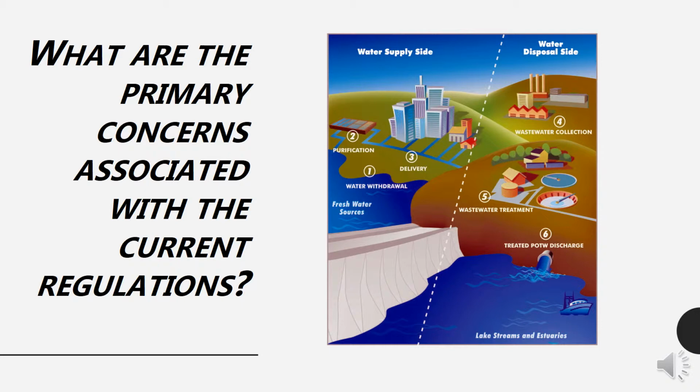Unfortunately, there is strong scientific evidence that the current Stage 1 and Stage 2 DBPRs fail to protect water consumers from exposure to potentially harmful species and concentrations of DBPs. U.S. regulations of DBPs have been updated several times since the first discovery of DBPs in finished drinking water in 1974. However, as argued by Singer in 2006, these changes have consistently failed to consider scientific evidence showing that the 11 regulated DBPs are inadequate surrogates for the complex mixtures, potentially hundreds of DBPs present in drinking water. Therefore, they may be poor indicators of the health risks associated with water use.